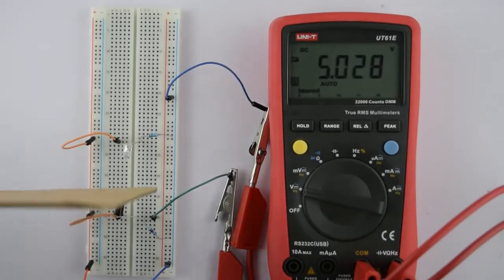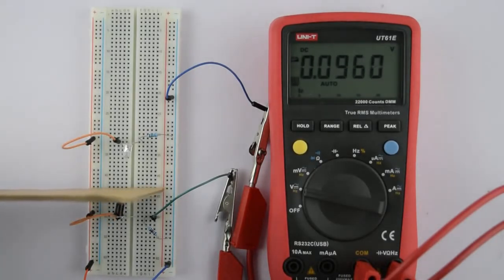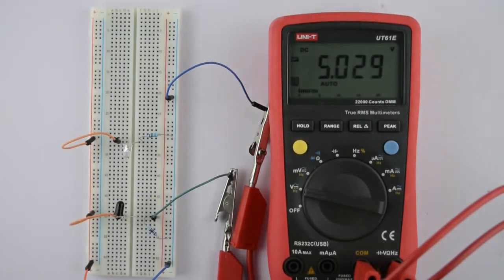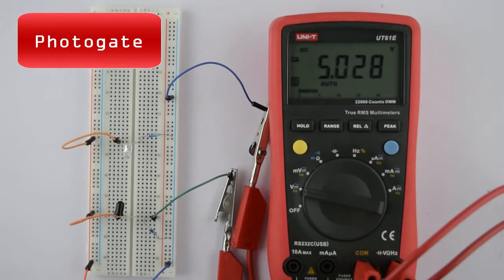If you'd like to take this further, the next step is to interface the output from the voltage divider with a GPIO pin and write a program to read when the GPIO pin is high or low. In another video, I'll show you how to use an infrared phototransistor to make a photogate, which can be